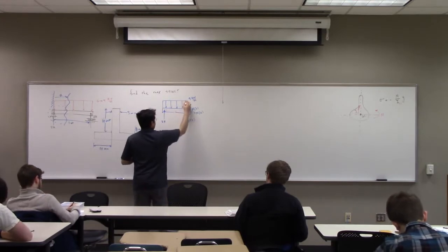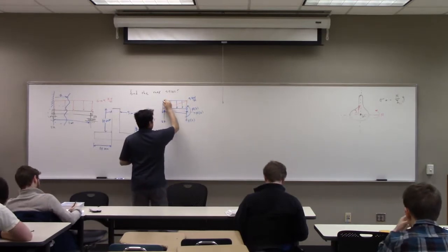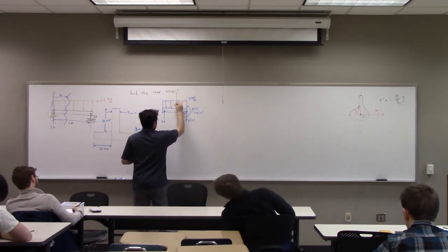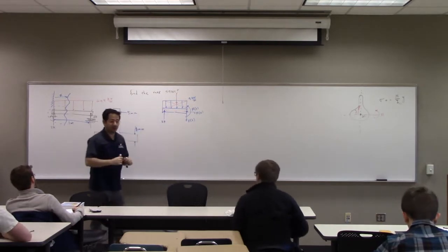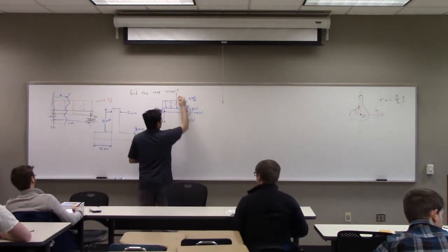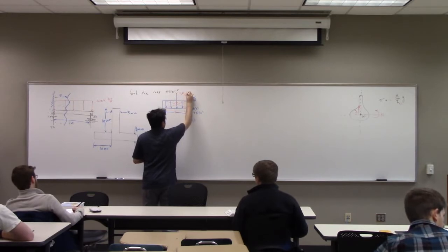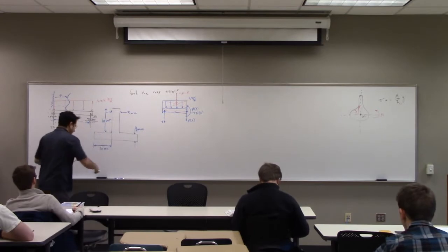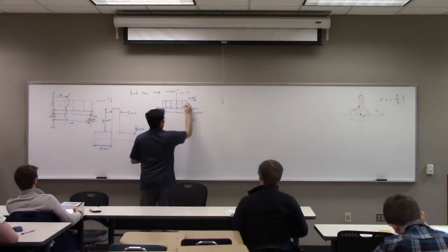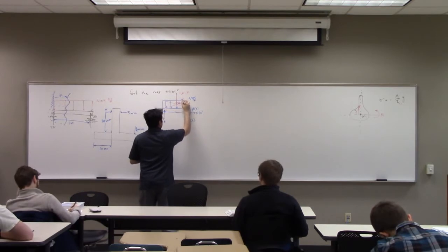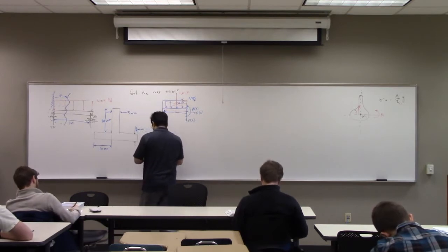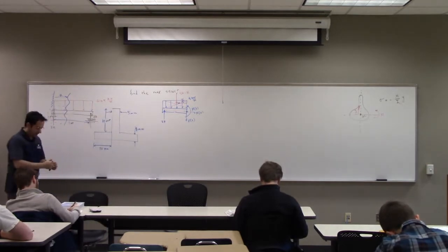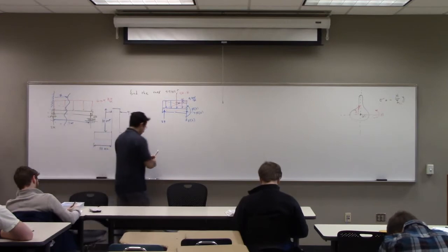So here, in step 2, the next thing I can do is replace this with a point load. What's the magnitude of this point load? The area under this, which is equal to 4K times x. And where is the location it's acting? x over 2 from here, both sides. So from here to here is half of x. So 4K times x and then half of x. So I'm just ready to write equations.